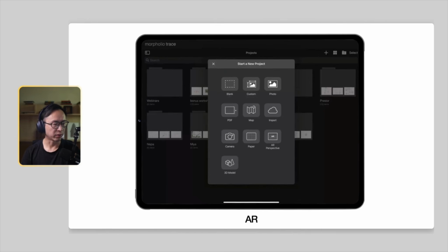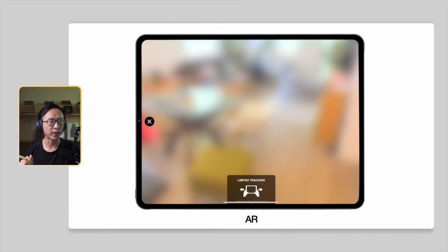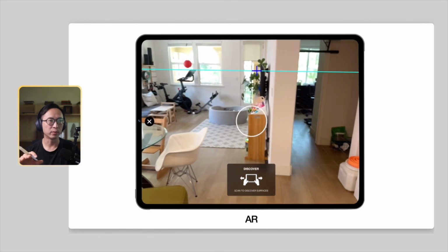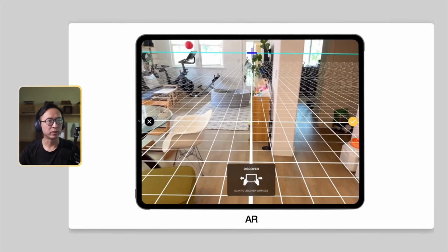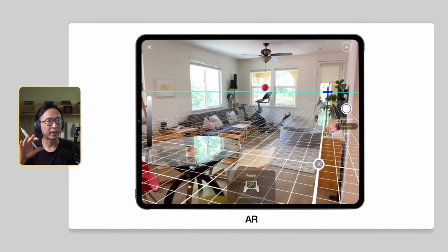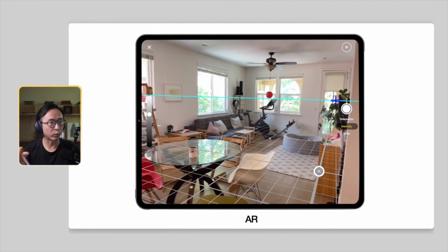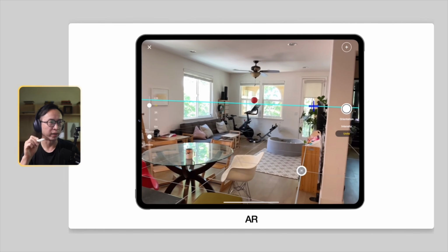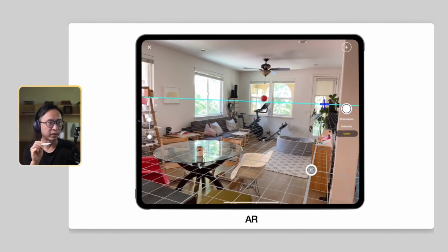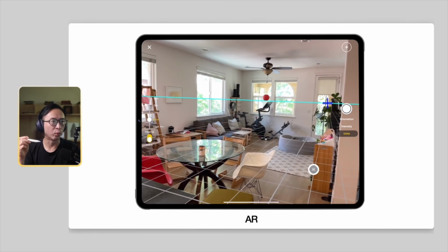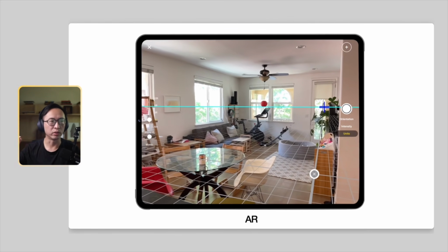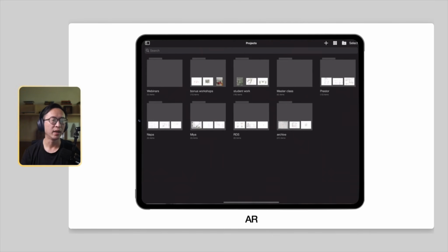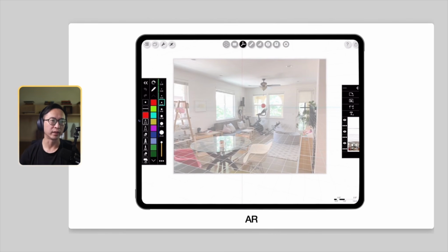And I'll show you this Lidar feature and I'll just voice over how to use this. So here, we're gonna use this AR perspective, and now I'm actually going to attempt to draw a perspective over this. So I'm using the built-in camera and the sensor to find the perspective in here. And after you do that, you can actually pivot your camera somewhere else to actually take the photo. You can even tweak the grid color so it's not so bright or dark. And you can see in here, I have the grid. You can set the grid to 1 meter, 2 meter, or you can do it in feet, into the units that you actually want to use when you're drawing something a little bit more precise, maybe like a table or something. And then you take a picture of it, and this will bring it into Morpholio Trace.